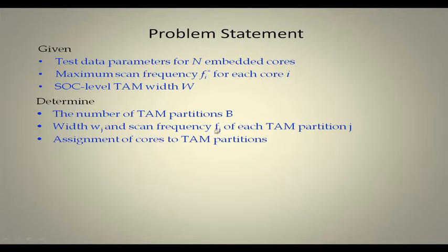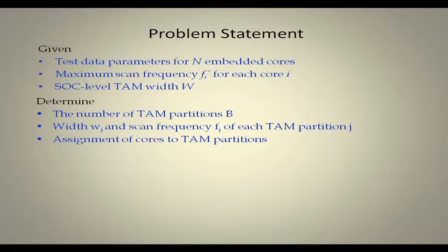This is useful if the ATE has got the feature that we can tell that okay, this number of lines we want to put on this frequency. So, the ATE has a restriction like how many out of the total W number of channels only V number of them can be put on say high frequency, but which V, if we have a choice. Then this particular formulation is trying to capture that situation.